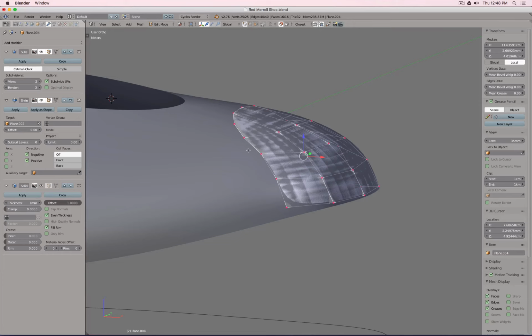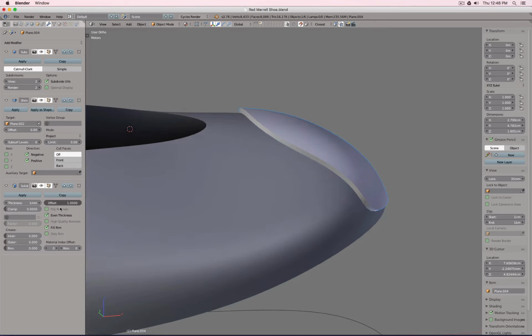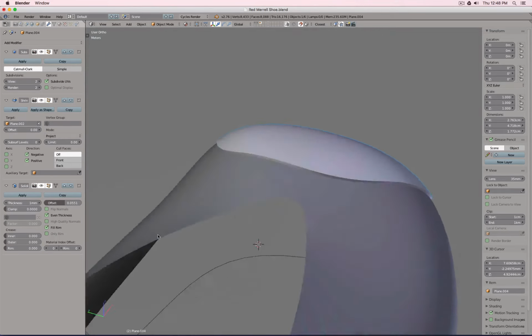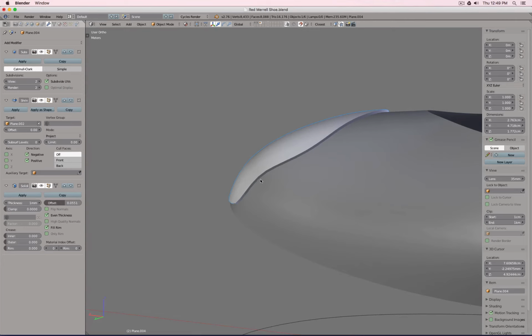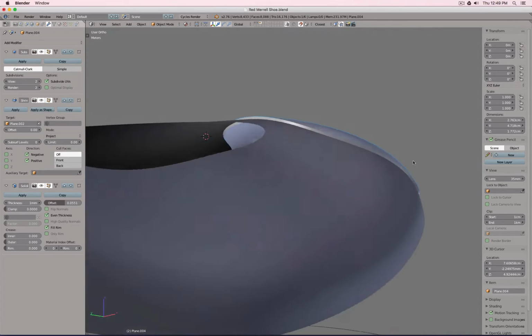Okay, Control N. Let's do a solidify so it sticks out. We can, for example, sink this mesh a little bit in, so it penetrates it internally, but it doesn't really matter because all I'm looking for is having this little groove here on top. And you see I still also have that shrink wrap command running at the same time.